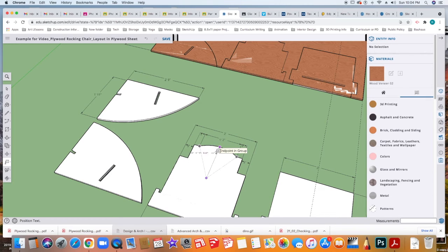I just have to make sure I know where that is. I'm going to click that and type in 1 foot, 1 and space 1/4 of an inch. And I'm going to put a little R in front of it, which indicates radius. That'll tell anyone what that radius is.